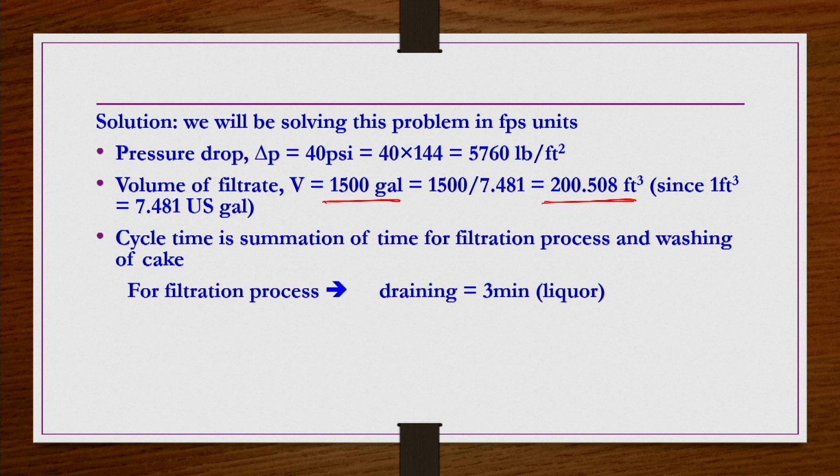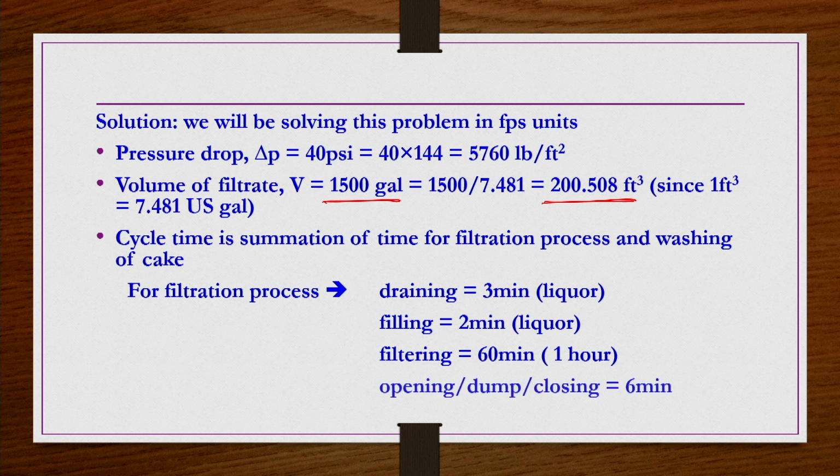So, for the filtration process, draining is 3 minutes, and then filling is 2 minutes. Filtering is done for 1 hour, so 60 minutes. So, that is 65 minutes, and then opening, dumping and closing is 6 minutes. So, 71 minutes is taken per filtration process.